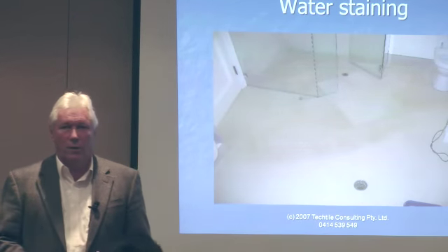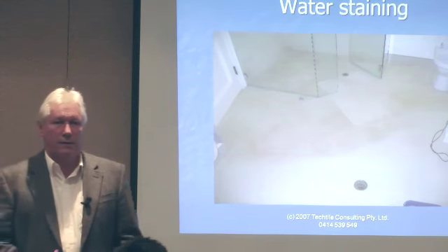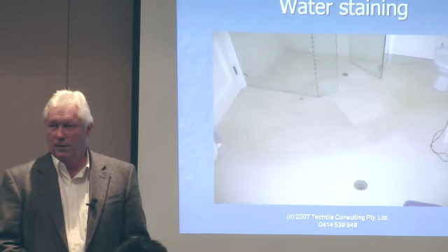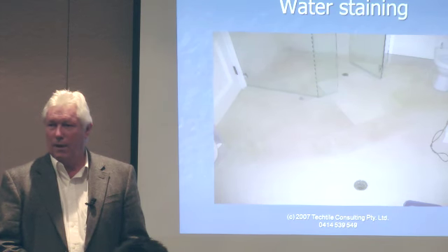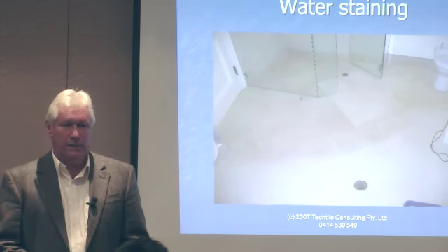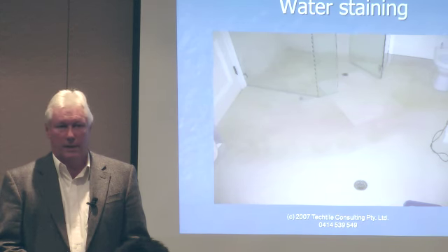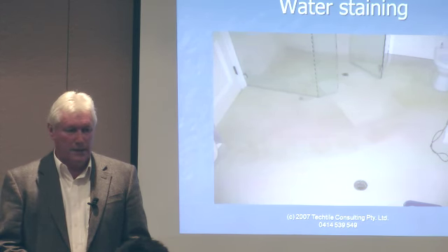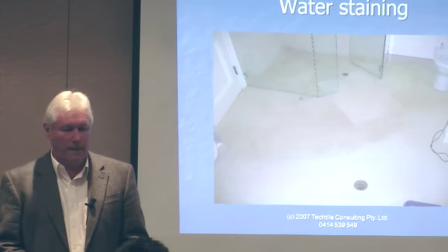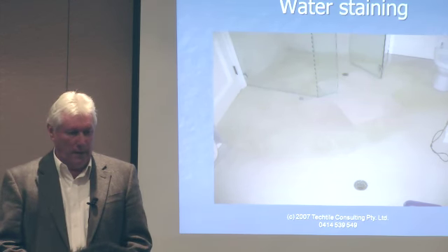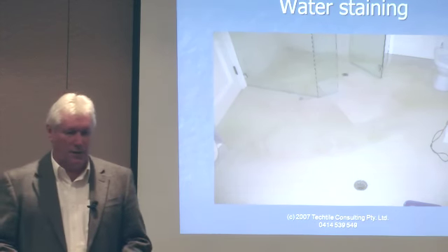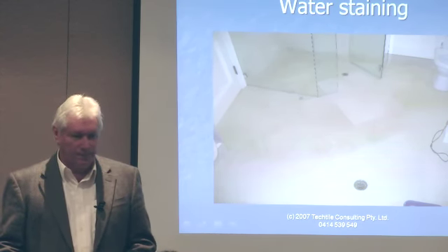So we knew which tile would work in which room, basically. We can get things like water staining, and stone, like lots of things, if you walk into the ocean with your jeans on and you get wet up to the knees, the bottom part of your jeans is going to look dark. And same thing happens with stone. As the water moves through, it can change the colour of it. And in this case, there's no water stop angle as required by Australian standards now, waterproofing code. And the moisture from inside the shower recess is moving slowly across the rest of the floor.